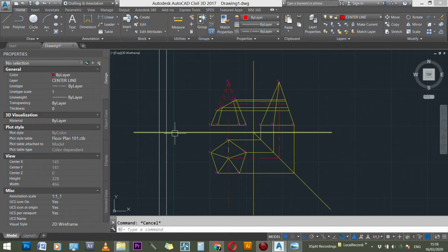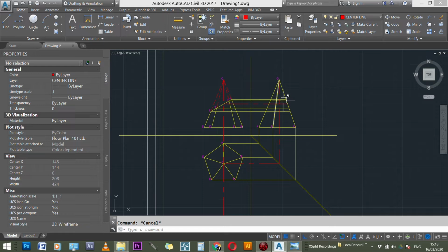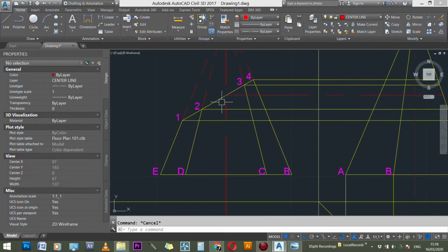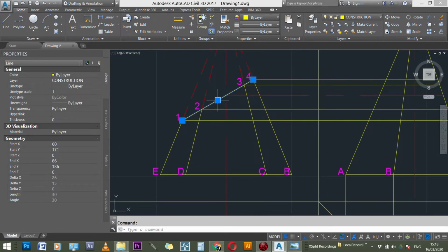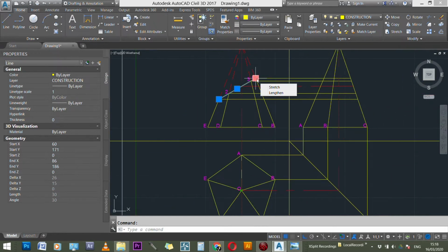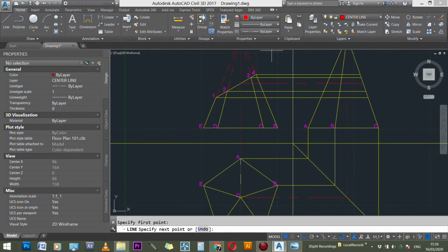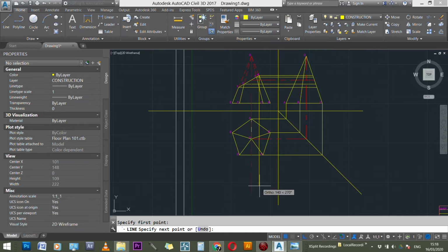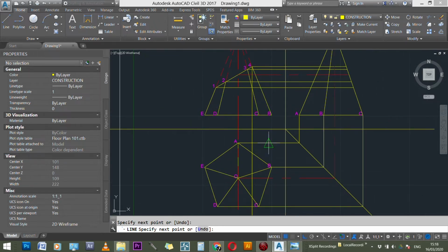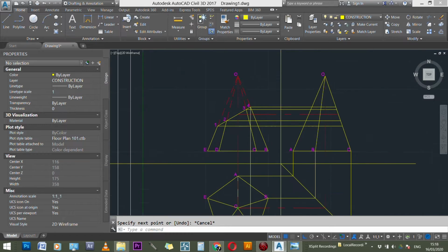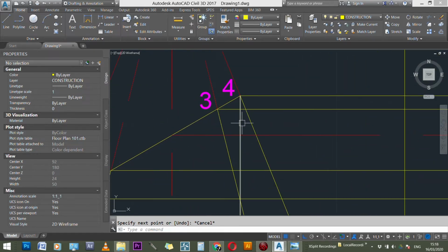And now what are we going to do? We need to create this cut shape. So the cut first appeared on our front elevation at points 1, 2, 3, and 4. What we need to do with these points now is transfer these down using our construction lines. Hit L for line, and from each point I'm going to project these lines down through the plan. We don't stop when they touch the plan, just send them through the plan.